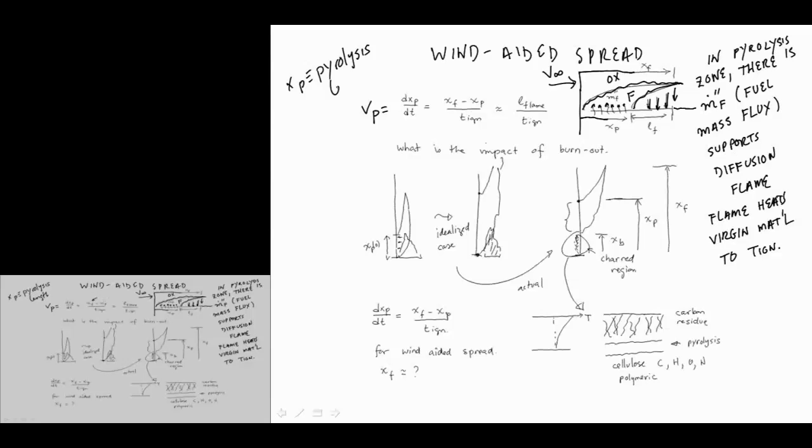And we said that that heating length, as you can see graphically here, is really the flame length minus the pyrolysis length. And again, burnout obviously occurs. If it's a thick enough sample, if it's a sample with some sort of ash content, you're not going to be able to burn all this fuel. All this fuel does not get converted into pyrolysis gases. So in the idealized case, that we'll see in one of the examples, there is no burnout. So I'm going to look at an example in Quintiere's book where he says, you have a sample of